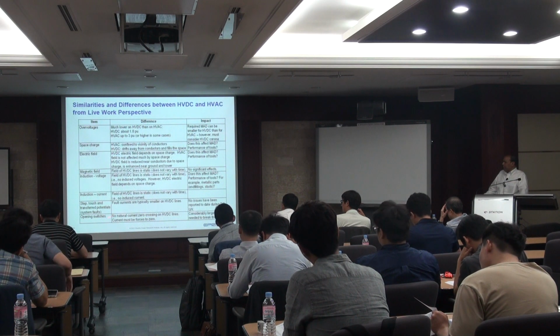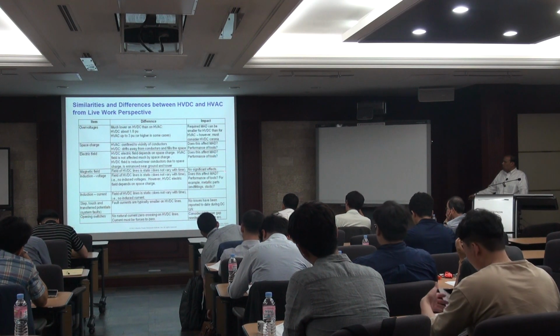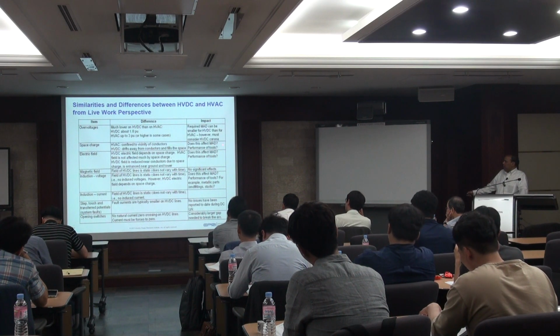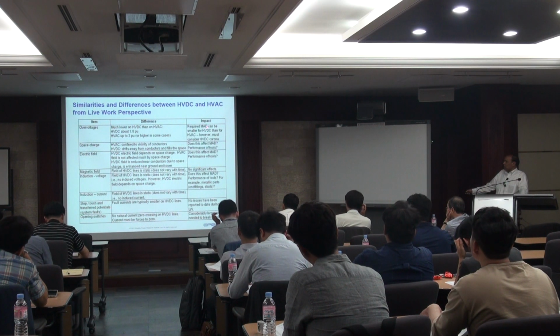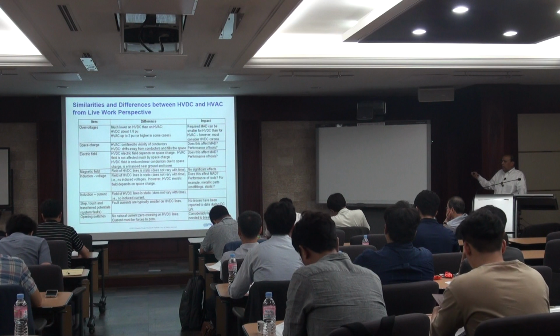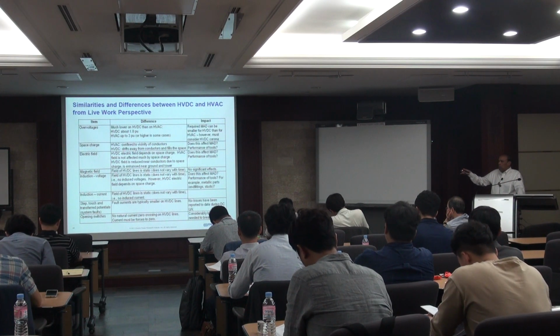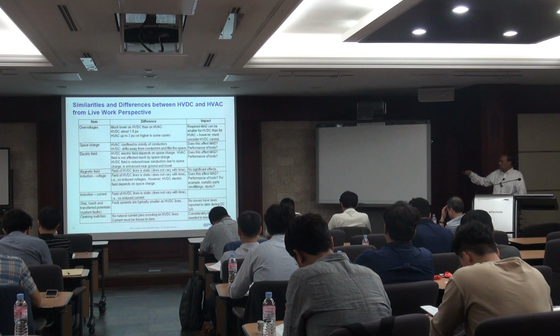In the interest of time, I may not go through this entire table, so it's a good thing for you to look at. You might wonder what MAD is. MAD is an abbreviation for minimum approach distance. That means, when you are working on a live conductor, how close you can go without being electrocuted. A person can go and start changing some things on the line. Because of the space limitation, we just call it MAD.